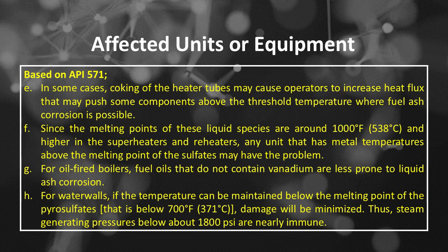Number H, for water walls, if the temperature can be maintained below the melting point of the pyrosulfates, that is below 700 degrees Fahrenheit or 371 degrees Celsius, damage will be minimized. Thus, steam generating pressures below about 1800 psi are nearly immune.